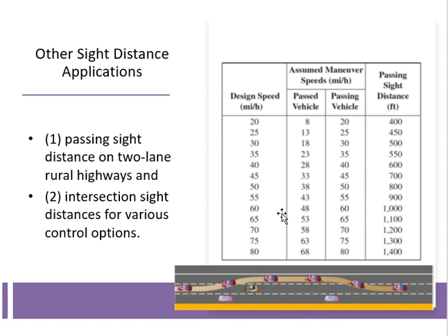It is the distance which you should be able to see to decide whether I should pass and then pass. Clear or not? Because every time you want to pass, you will not pass because you don't have the chance. Get my point? But to decide safely whether I should pass or not, you should have passing sight distance available.